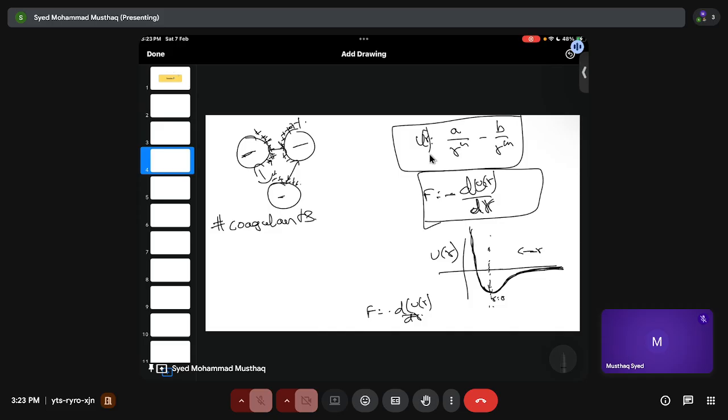See, now this is about coagulation, and when coming into this coagulation theory, what happens is, suppose this is your surface, right, and suppose I add some inorganic charges. It has a negative charge, so this becomes positive, and finally they get attracted, right? Because of this attraction, this happens while the particles are in motion. So when this surface moves, they get attached, so they also start to move.